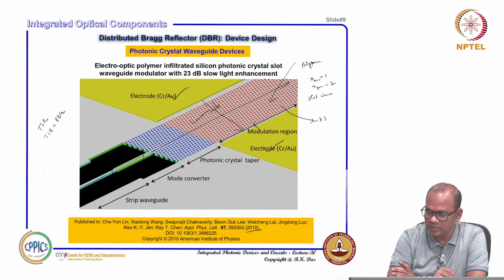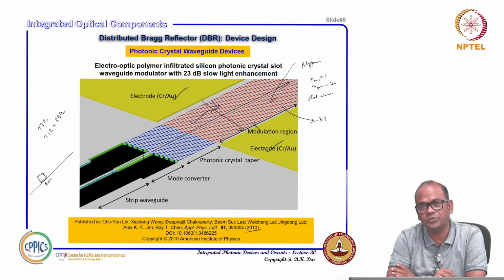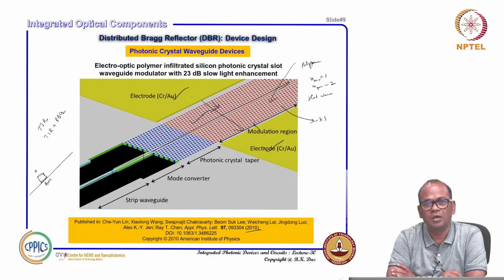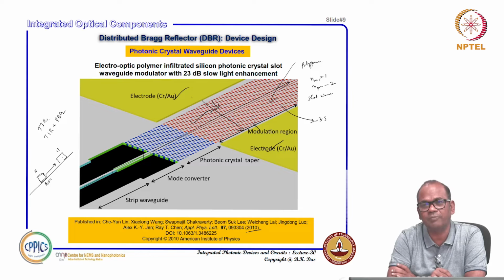So, that slot waveguide, what it is, you know, suppose you have a device layer, you are creating a waveguide. It is your oxide box layer, and this is your device layer, you have a waveguide, and to confine, to support a fundamental mode, you need a particular width, below which it may not confine a guided mode. Okay. Similarly, if you want to have another waveguide far apart, single mode, it can be guided, and if they are far apart, they will not be coupled.